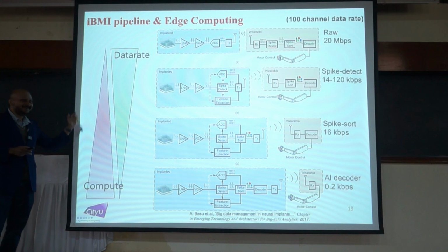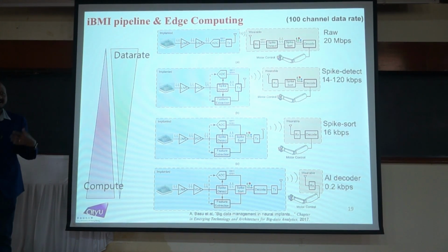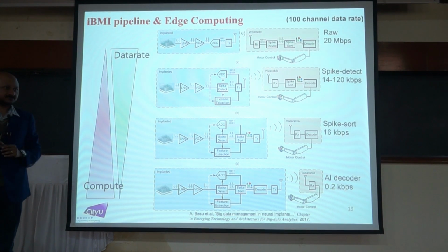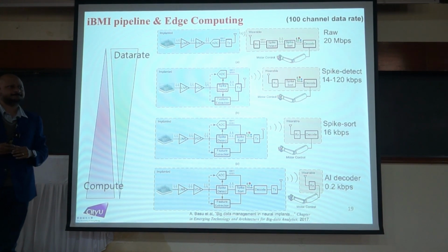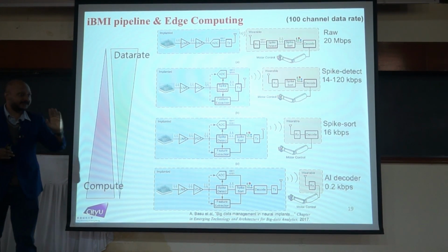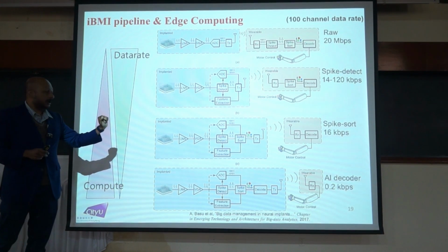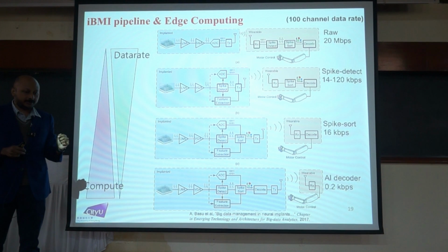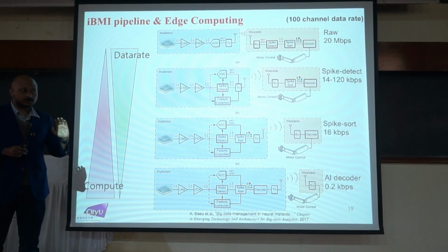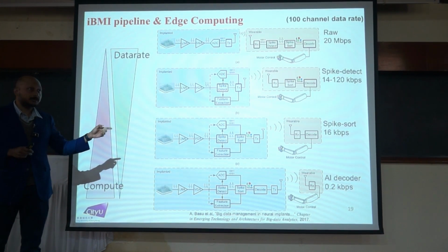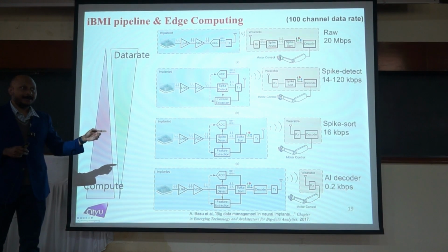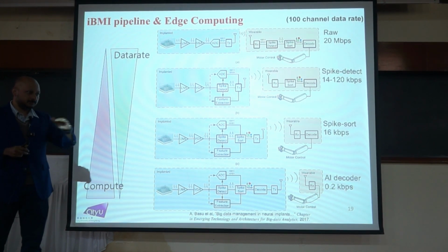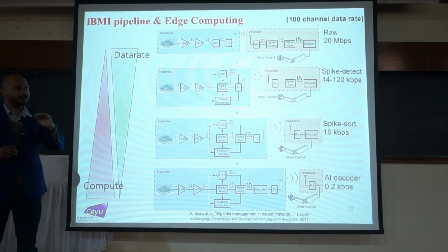As I showed earlier in my motivation part, we are trying to do something that's more of a neuromorphic solution, so it's not a pure digital spike sorter. Yeah, it's a mixture actually. I will qualify that. In the work that I have done, we have actually removed the spike sorter. We don't use it because spike sorting is not so necessary for the decoding that we are doing, and it actually adds more non-stationarity to the data. So just doing decoding is good enough, more robust.